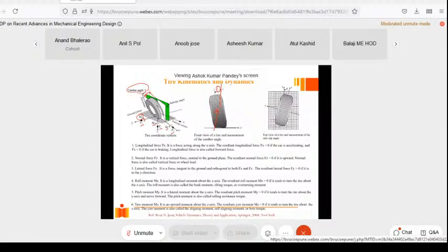Camber angle is a very, very important influence. For some of the vehicles, we tilt the wheel outward, right? So the forces that you're going to find also need to consider this camber effect. When you see the tire from the top, in the front portion you have this angle which we call the slip angle. This you come across when you look from the top.